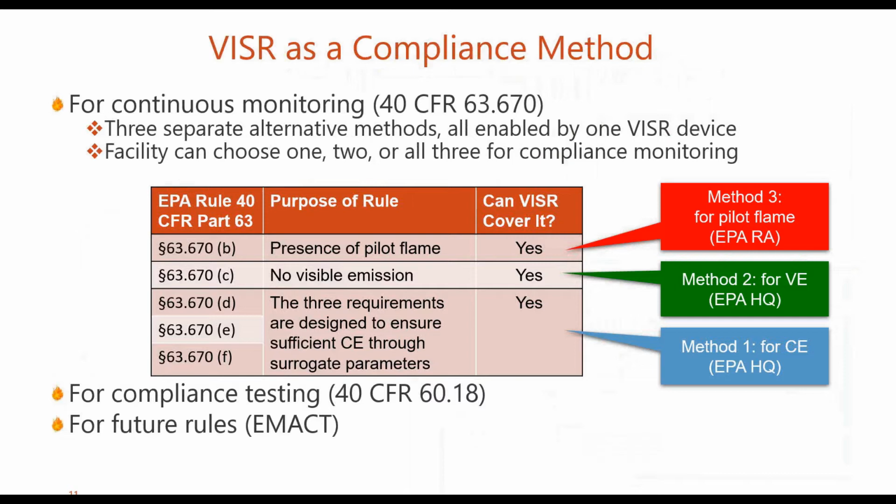The rule specifies the indirect method. So what you would be required to do is to use an online GC or a calorimeter to monitor your process stream, determine the BTU content of which you're sending to the flare. You would also need to monitor the pressure and temperature of that stream to correct to standard conditions.